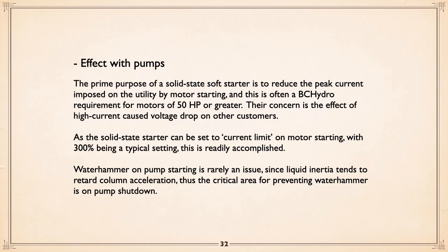Now, this is all great fun. It serves two purposes. One is to say the solid state starter will do a nice job of ramping up the voltage, which ramps up the current, okay? And in fact, reduced voltage starters are required, BC Hydro, anything 50 horse or greater. Again, the effect of this stuff on nearby residents and whatever.